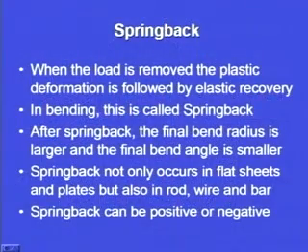Spring back is not only found in flat sheets and plates, but it is also found in rods, wires or bars. I have given an example of a sheet. If we take a sheet and bend it, there is going to be a spring back action, but it is not a phenomenon limited to sheet metals or plates only. It is a common phenomenon if we try to bend a rod. You take a rod of any metal and try to bend it. When you leave it free, it is going to slightly open. That is a spring back action.